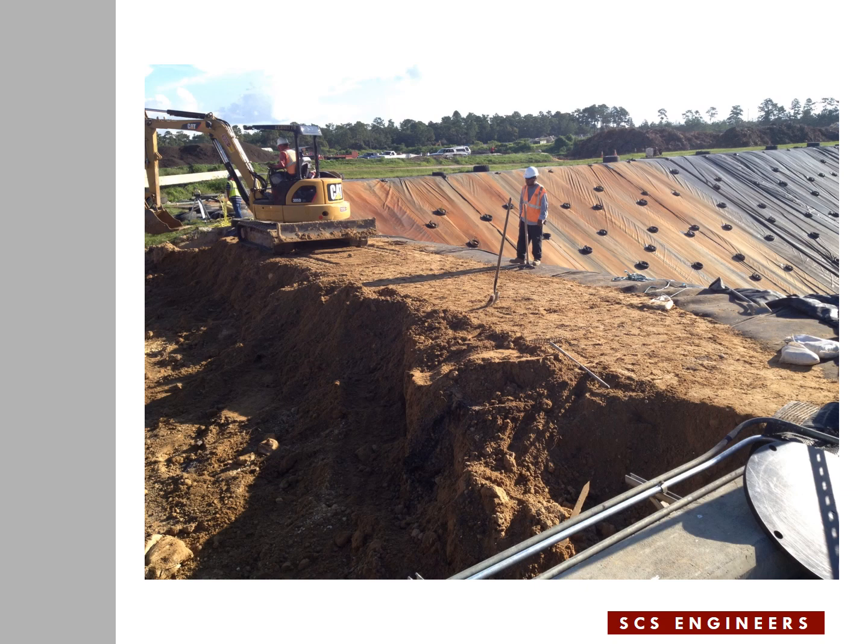In this picture, it shows that the anchor trench is completely filled, where the guy is standing with the shovel in front of it. What used to be the anchor trench is completely filled to the top of the anchor trench. Now the small machine is creating a new anchor trench for the upper geogrid layer, because they wanted to secure the upper geogrid in a much larger anchor trench that would make it independent of the previous anchor trench.